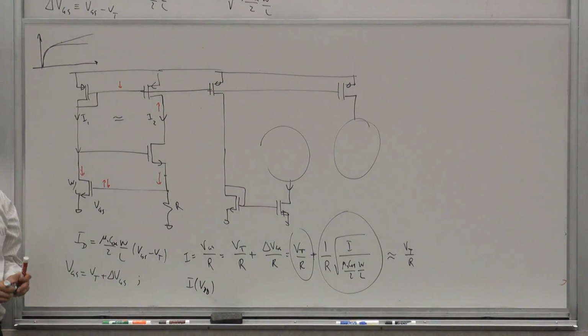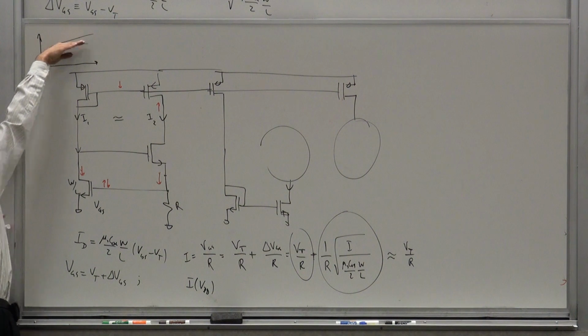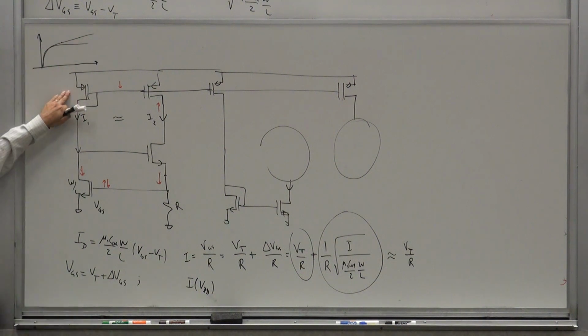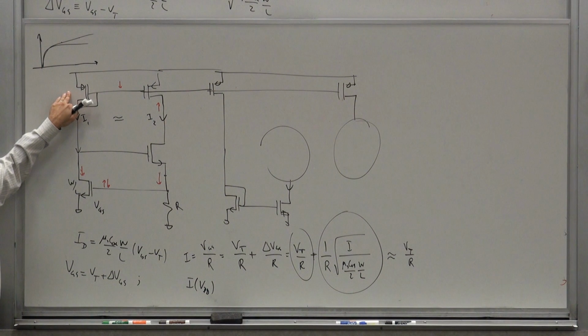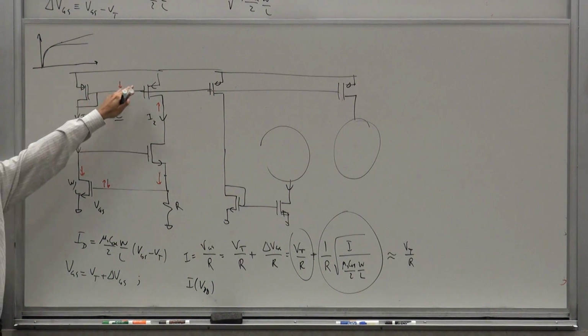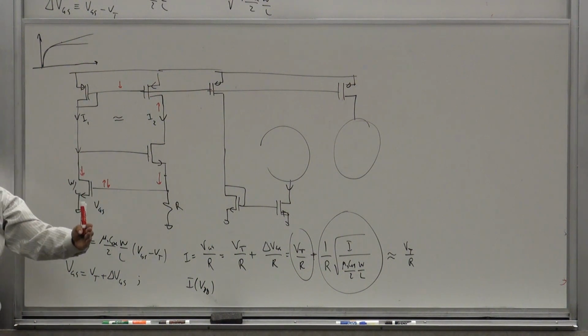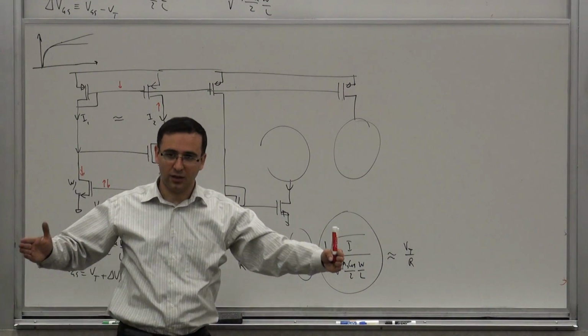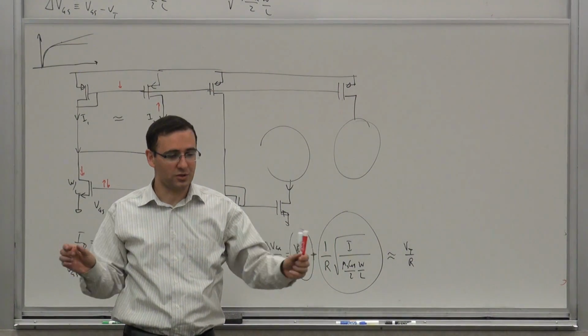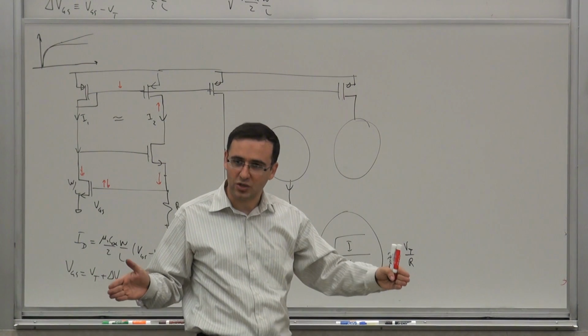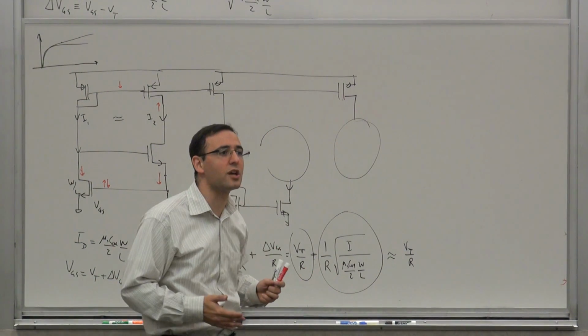And he's right. Right? So what do we do if let's say that was too much? We have reduced that effect because the slope of this line is not very large. Particularly if you use a large enough L. That's another thing you can do. You can make the channel length of these guys larger so the output resistance becomes greater, and that means that you get less channel length modulation. Because if you make your channel long, the same fluctuation in the voltage results in a smaller fractional change in the total length of the channel, and therefore the percentage of the current change will be smaller.